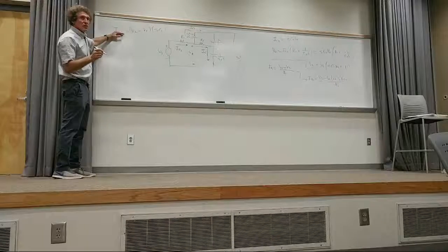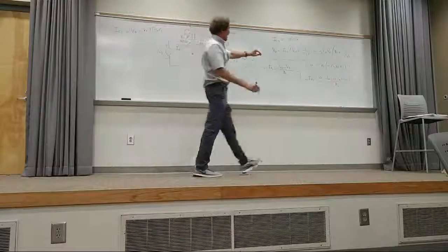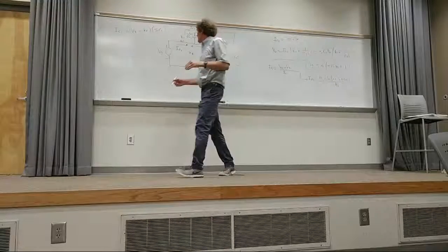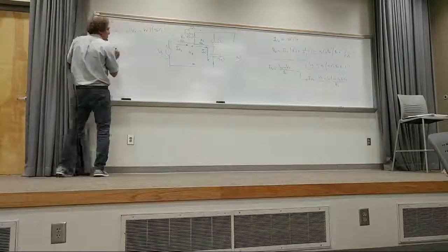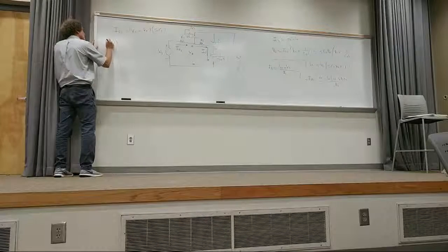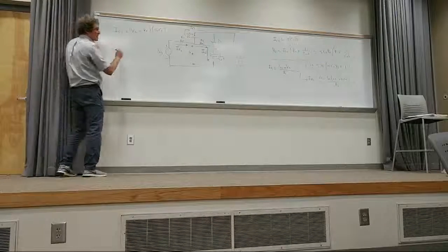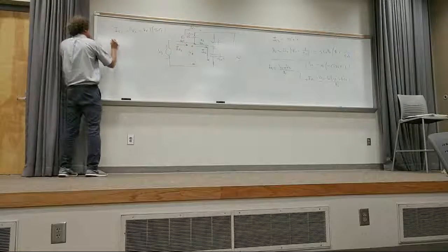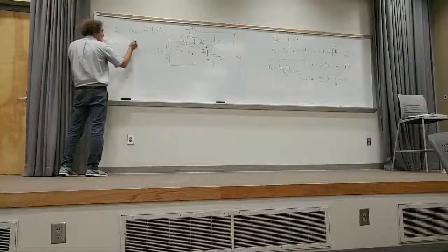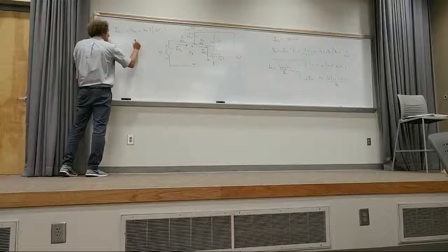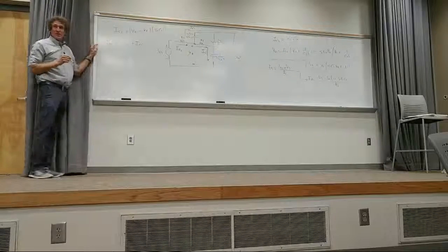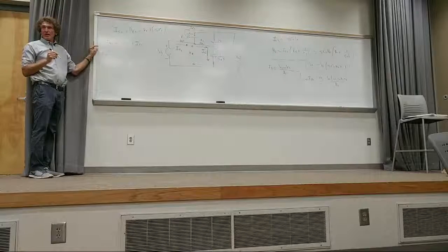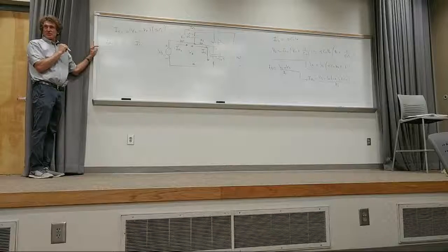I've got IC1, I've got IC2, and I've got IR1, right? Well, we said that current goes up. So what's the final equation? We have IR1, right? That's going that way into this junction. What's it equal to? IC1, right? Plus IC2. Do you all agree with me? I want to make sure you see why I'm going to write what I'm writing. Are you with me on that? Now fill it in terms of the voltages, V out and Vs.